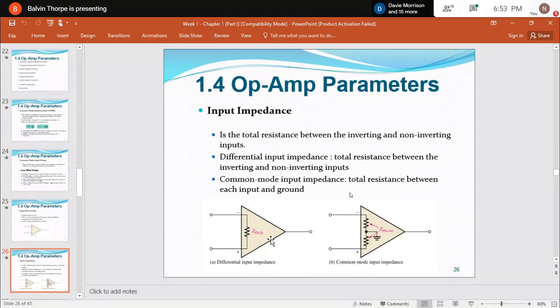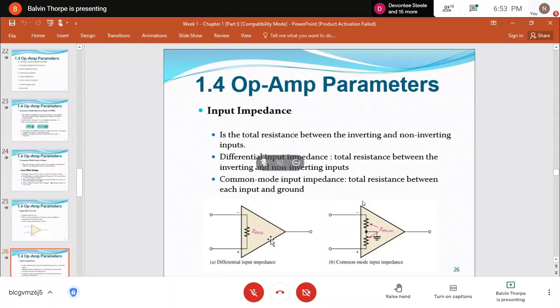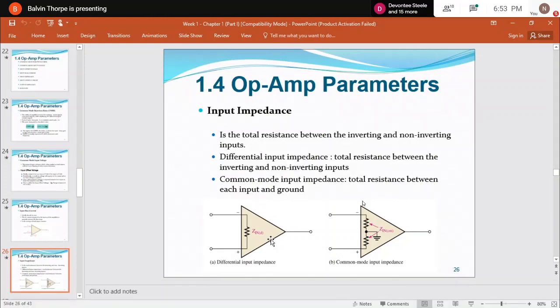You don't have to put a figure to it because every manufacturer has a different value. So if you apply a voltage to the input, causing current to start to head towards the input, if the input impedance is very high, then current is not going to go into the amplifier, not true? Because current doesn't like high impedance. Yes, sir. Okay. And therefore, the truth be told is that there's no current that goes into the amplifier. So then how does it provide amplification?